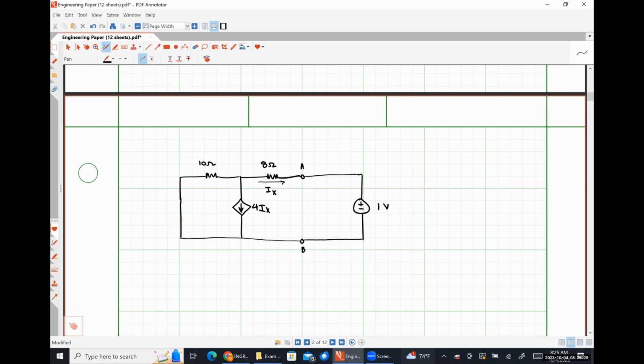That's typically how I do it as well. Just a 1 volt voltage source or a 1 amp current source. Unless I have kilo ohm resistors, and then I might use a milliamp source just so I don't get ridiculously large numbers.